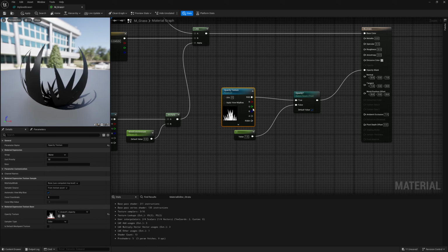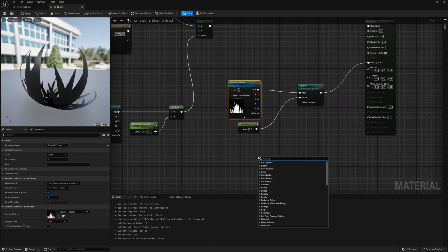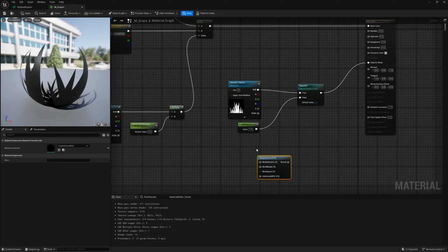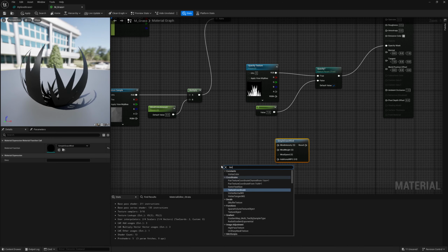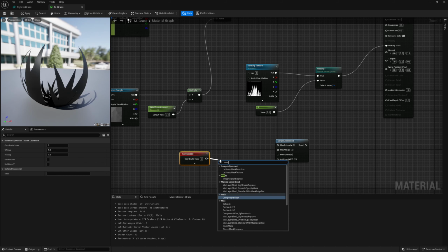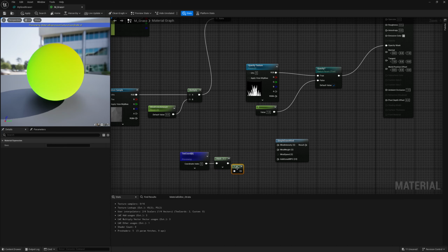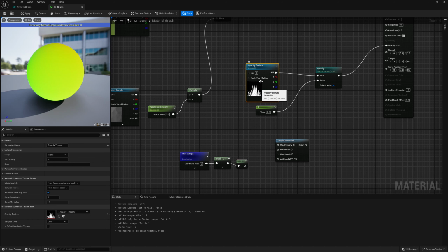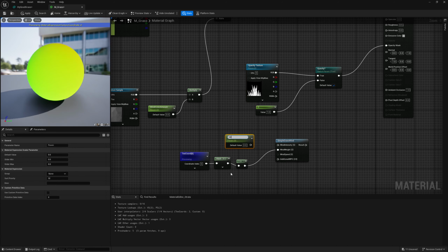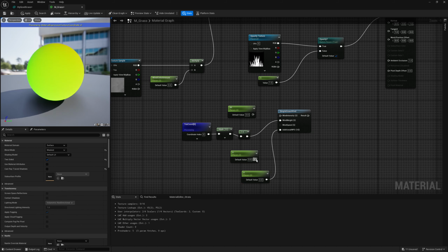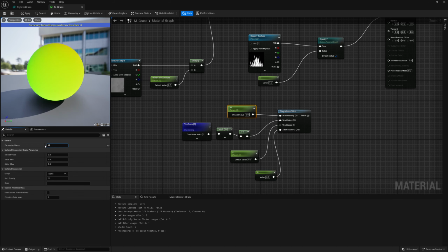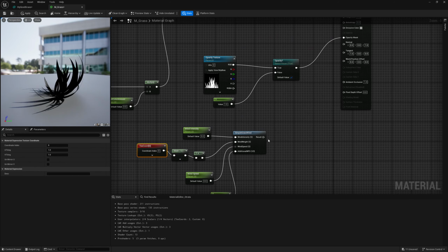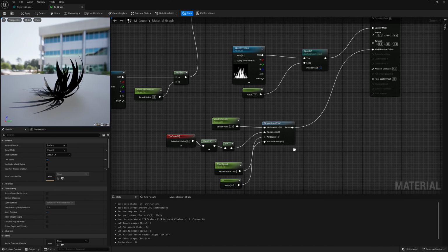and we're getting that awesome alpha map. Now to get our wind, we're going to look at the world position offset, and we're going to do something simple with simple grass wind. And we're not going to do anything too complicated, but I want to get the texture coordinate of our grass, and I want to mask the Y channel. We're just making sure that in this texture, as it goes from low to high, it's getting more windy. We'll create 3 parameters for all 3 of these. Let's not do it for that one. We're going to have a constant set to 0 for the additional WPO, but I do want access to the intensity and speed. So we'll call it wind intensity, wind speed. We don't have to keep previewing this. We'll plug it into world position offset. That is actually our wind completely finished.